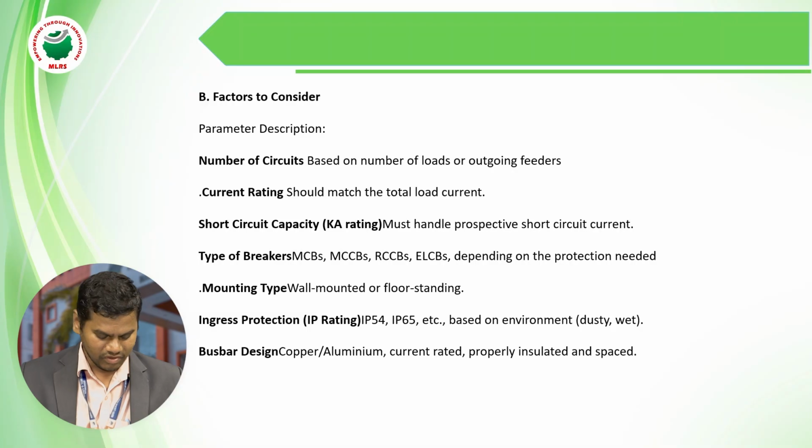And the mounting type. In mounting type we can consider only wall mounted or floor standing. And ingress protection, that is the IP rating, IP54 and IP65, etc. And based on environment, meaning whether the area is dusty, wet or dry. And the last one, bus bar design: copper or aluminum, current rated, properly insulated and spaced.